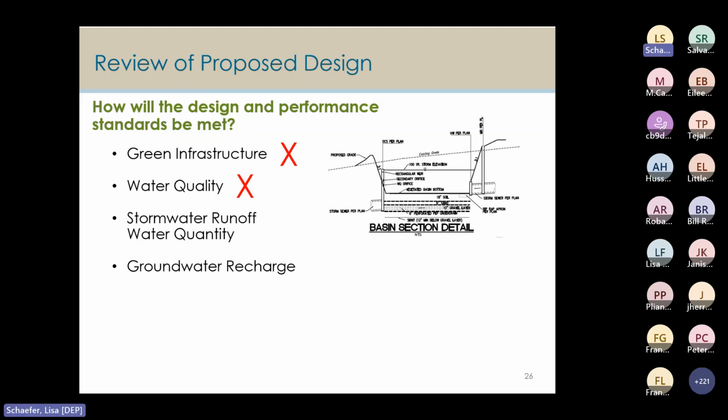Now, interestingly, the stormwater calculations that were prepared earlier in 2022 use the Type 3 storm distributions for the 2, 10, and 100-year design storms. But as per the 2021 publication of Chapter 5, and as Anthony said earlier, NOAA C and NOAA D distributions are now used. So that would also go in the review letter, and I would have to see new calculations. So far, it's not looking good for meeting runoff quantity control. And so I'm going to call this an error on the play.